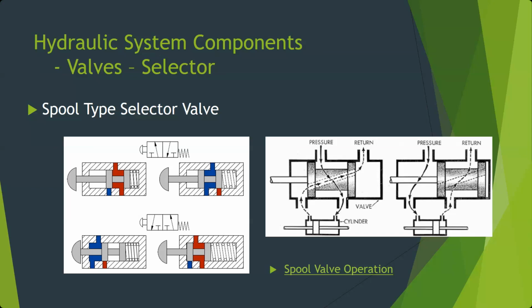So in the case of this upper valve, you push it in, you see the springs compress, that ports fluid to the red side. When you let go of it, it's going to push it back this way, and that'll port the top and blue ports together under normal circumstances. So just kind of shows some different things happening there. But most of our valves are going to be this, or they're going to be a servo or a pilot valve like we saw in the video a second ago.